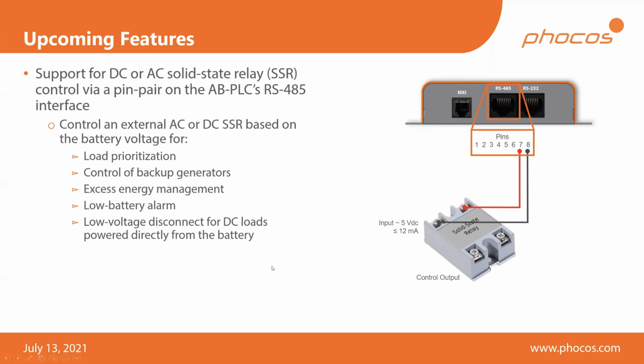And the last point is a low voltage disconnect for DC loads. You might want to mix AC and DC loads in your power system. And this is a good way to manage those DC loads. I actually have an example, so I'll mention that in a couple slides.